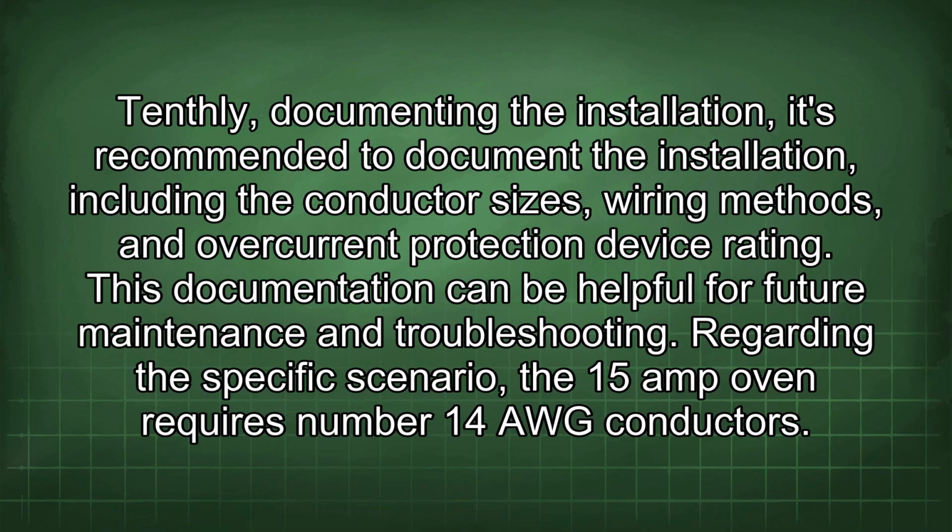Tenthly, documenting the installation. It's recommended to document the installation, including the conductor sizes, wiring methods, and overcurrent protection device rating. This documentation can be helpful for future maintenance and troubleshooting.